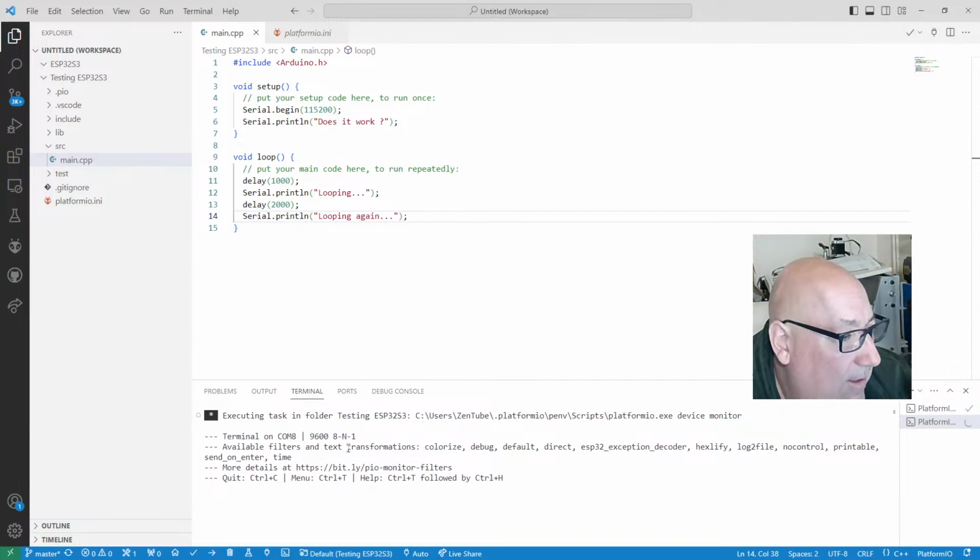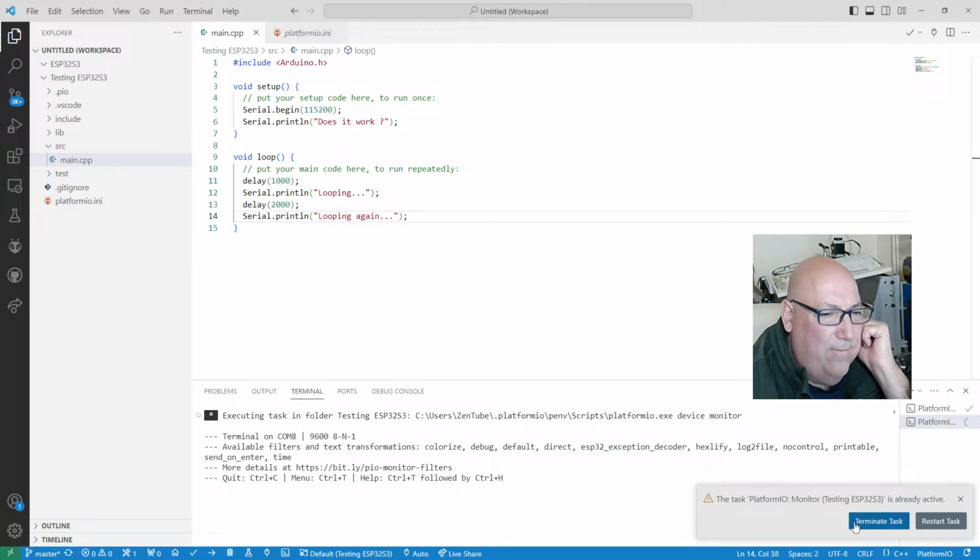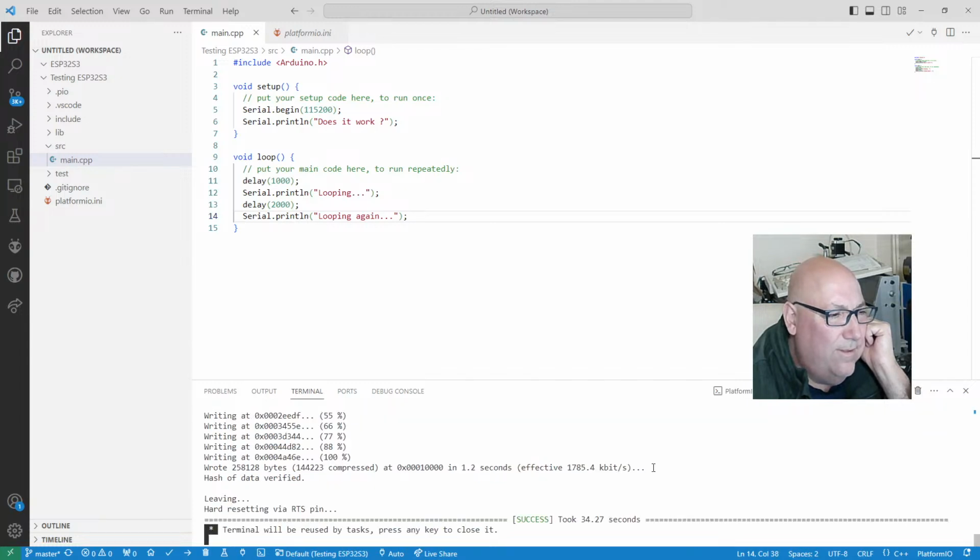Right, let's try. That's a reboot. I'm not liking this controller. Not liking it at all. If you can't do a reboot and watch the thing reboot, I'm not a fan. I suppose you've got to set up a NeoPixel on a pin and change the colour. It's the only other way of going to get feedback out of it without the serial port working. What am I doing wrong with the serial port, I wonder?